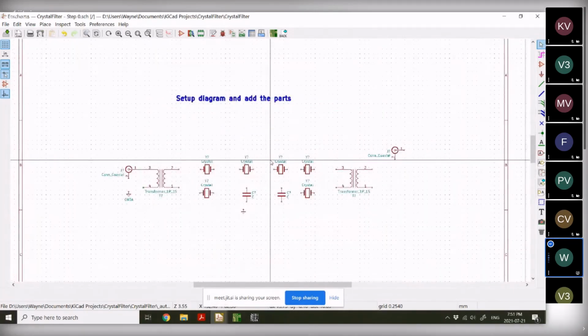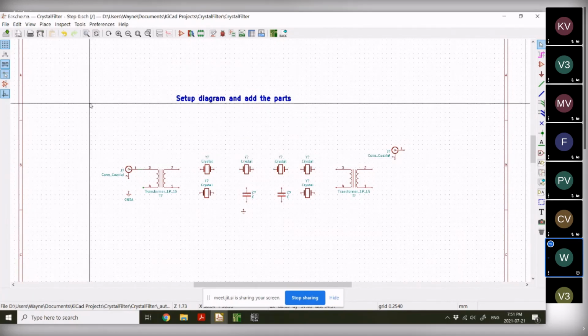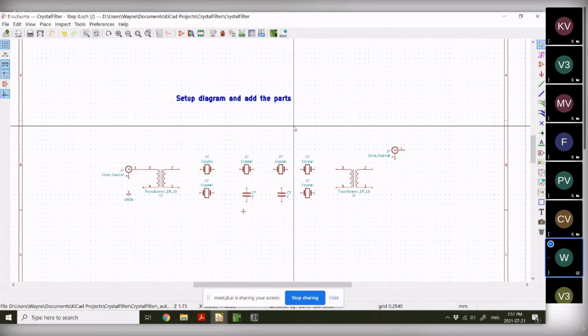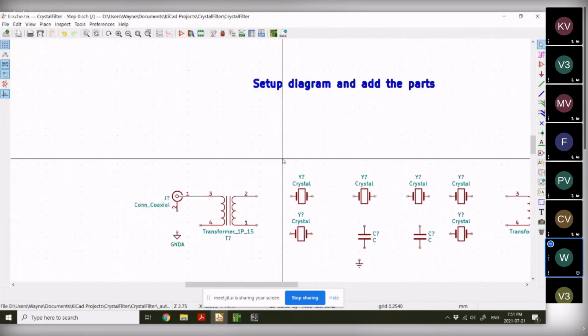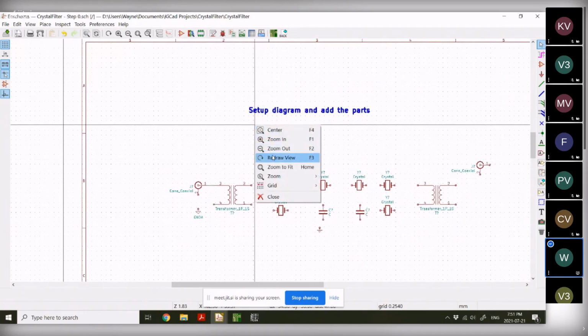So if you've used LT-Spice, there's some things that are similar. I mean, it has the same capabilities as the schematic editor in LT-Spice, I would say, but all the keys that you would select to use them for are different. Now, when I'm actually on the grid, you have zoom in, which is a function key. F1 is in, F2 is out, etc. You can learn that if you want. I use the mouse, so I never bothered to learn these things.